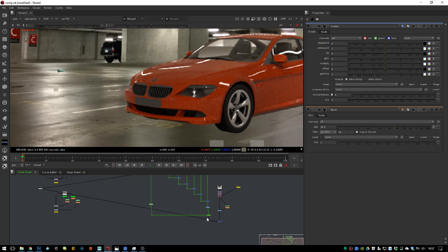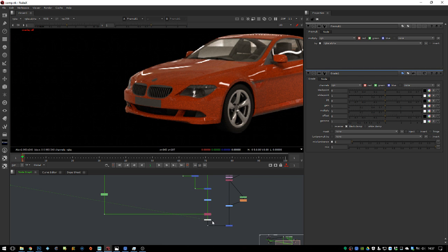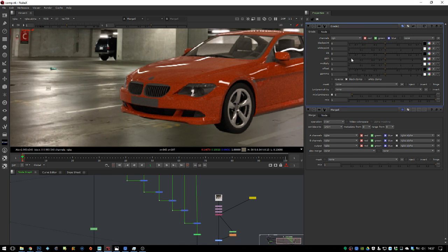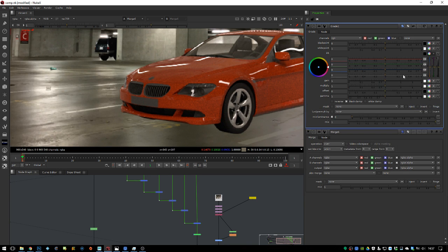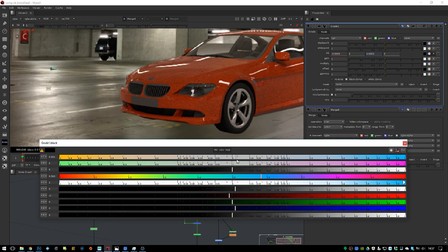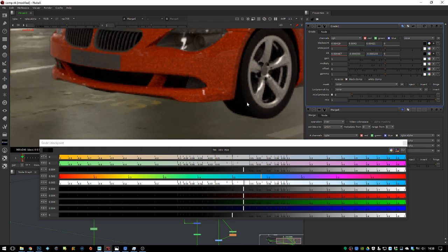So let's just do the premultiply right here. Save actually. So that's a premultiply, and then it's unpremultiplied. So now you can, if you want to, increase the blacks. This is a dark gray, so we definitely want to bring up those blacks like this. I would just really subtly eyeball this using lift or gain. Then you would slowly bring in some color to this if you want to match the tints. This would be really subtle. You would check these values, go to the black points, and increase the black points really subtly to something maybe like this.